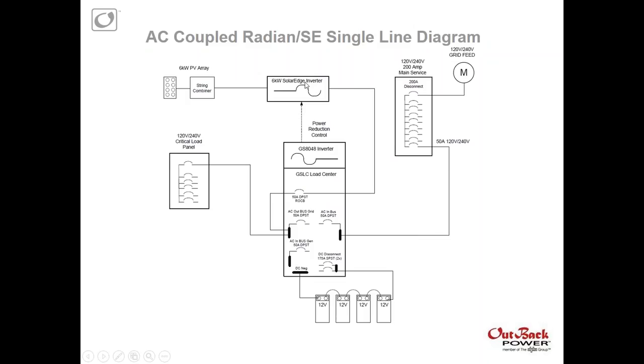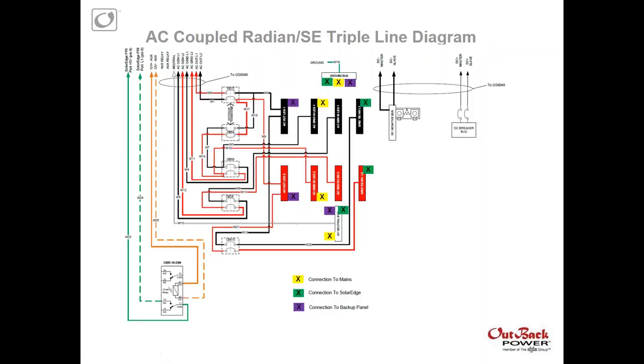Now, when the grid is up, one key point here is we are just a wire. So there is no efficiency lost in your grid tie inverter sending the power to the grid. It's only when the power goes out that we're doing anything with this. So it's an important thing to remember for the efficiency of those guys.